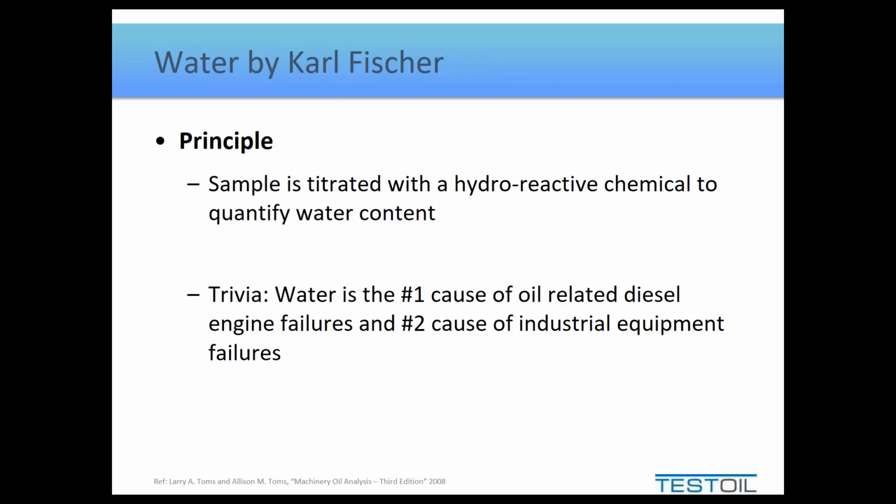Quick little trivia point there: water is the number one cause of diesel engine oil related failures. It's the number two cause in industrial equipment. If you're curious what number one in industrial equipment is, it's particulate. So, back to the particle counts.